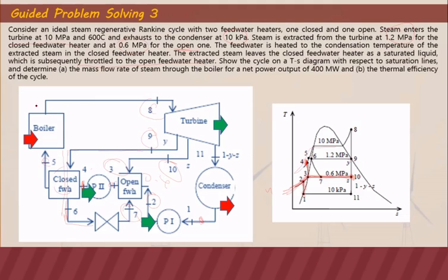And then now it is at 0.5 entering the boiler. At here, as you can see in the TS diagram, we just assigned it here because we do not know where it really is. And then we added heat in the boiler, heating the steam to 0.8. It will make it superheated vapor at the entrance of the turbine. And then it will expand to 0.9, 10, and 11 here, as you can see. 9, 10, and 11 at the exits of the turbine.